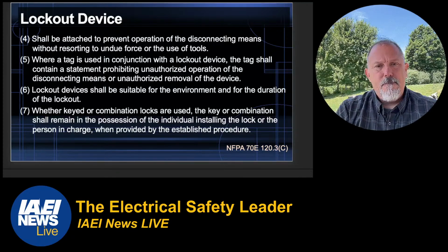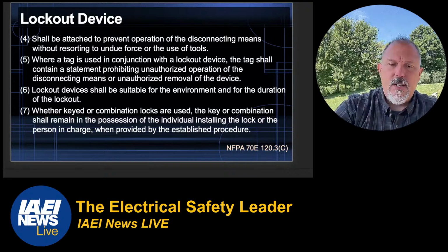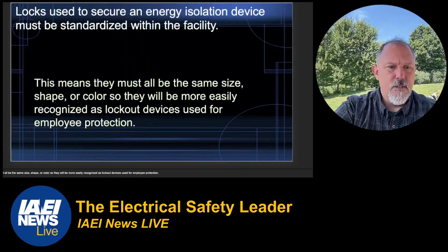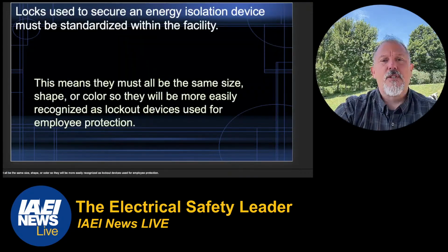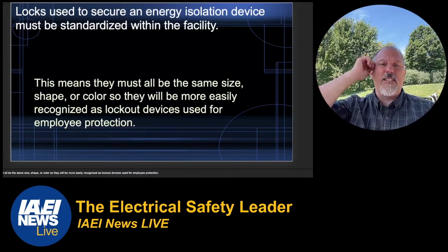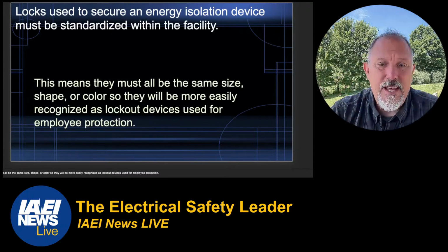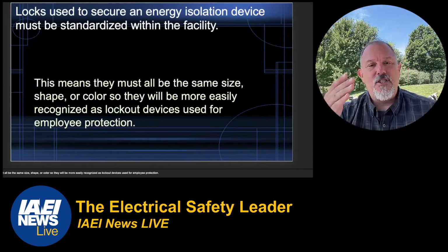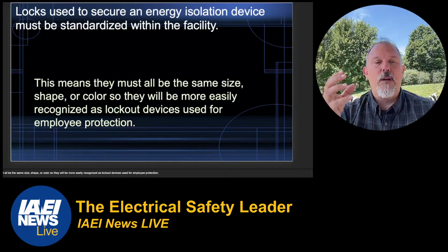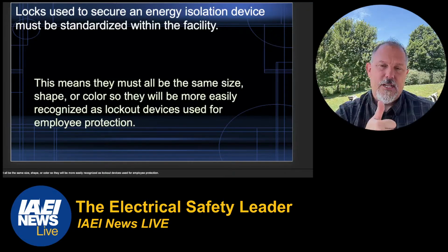Okay. Shall be attached. Where the tag is used, we already talked about those. Locks used to secure an energy isolating device must be standardized within the facility. They must all be the same size, shape, or color so that they will be more easily recognized as lockout devices used for employee protection.